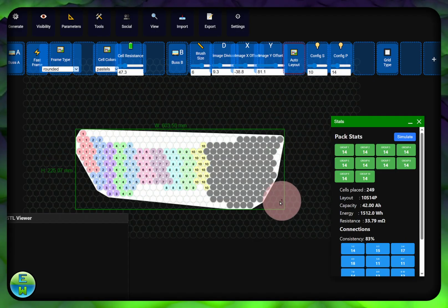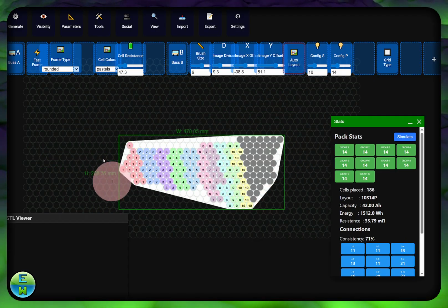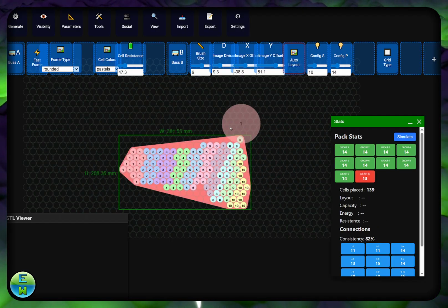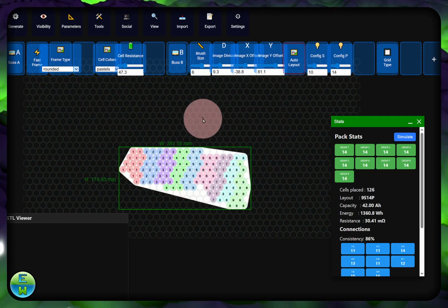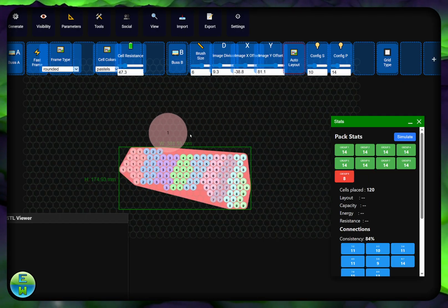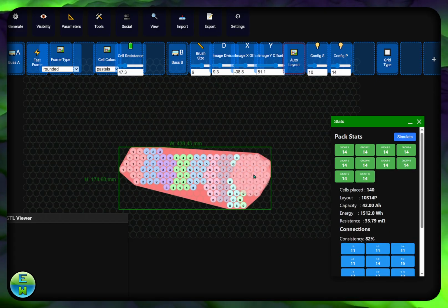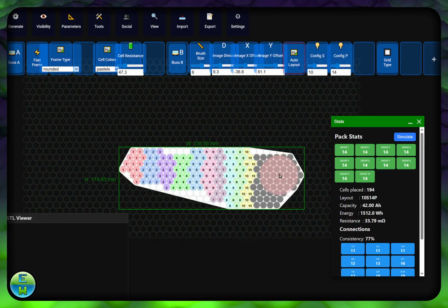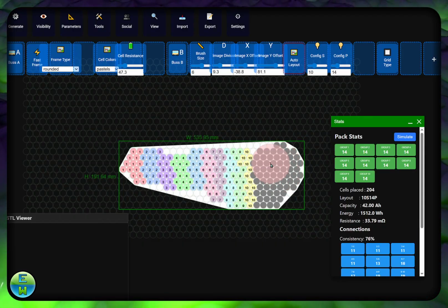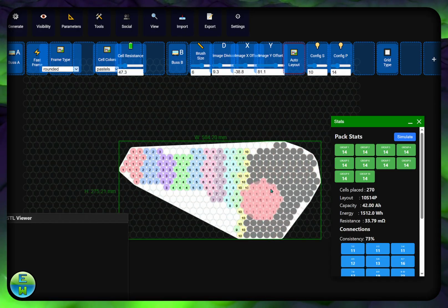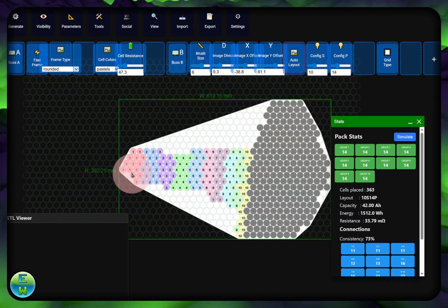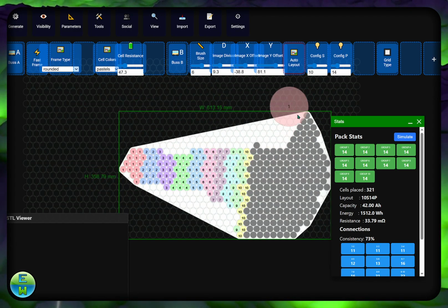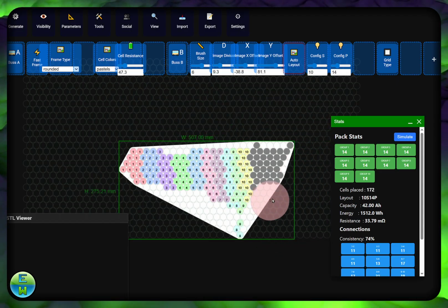So we can just find the battery. Obviously we don't want a battery that shape, right? The frame is red when there's an uneven amount of cells in the series groups. So it'll be totally white, and that's just because I have those for my colors. You can set your own colors. In this case, it's totally white no matter how many cells I paint because it has enough cells to make all the groups. And there's not an incomplete cell group.